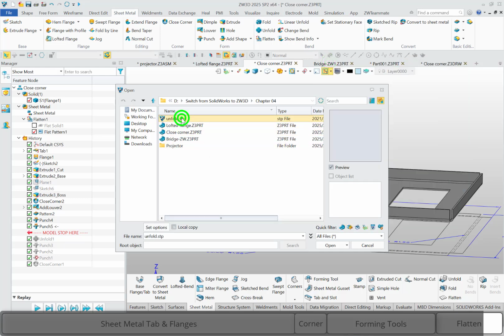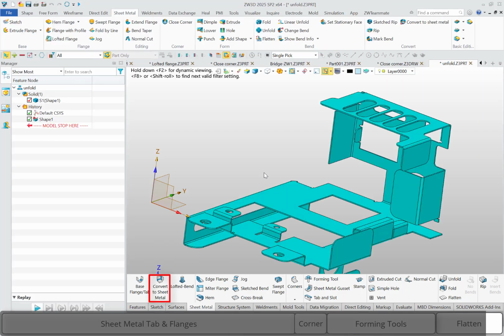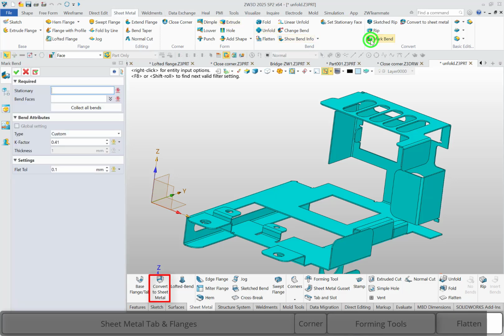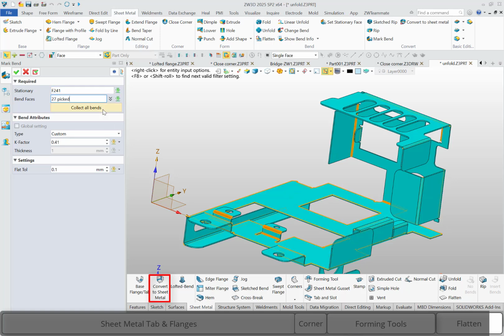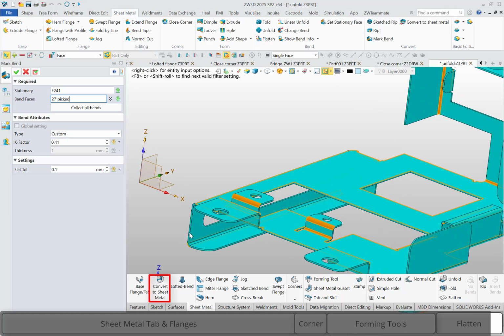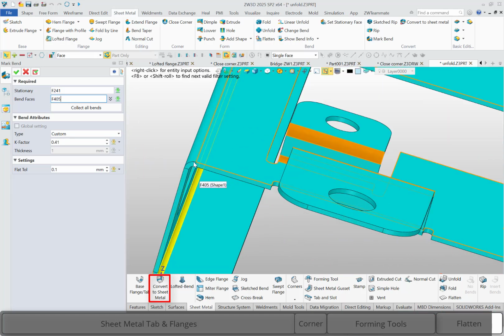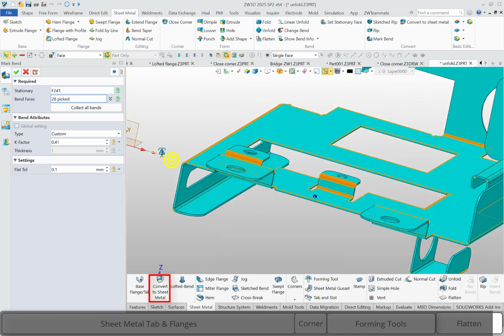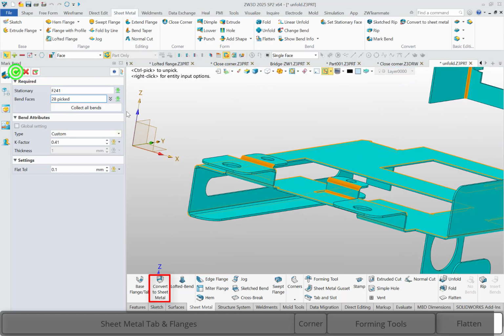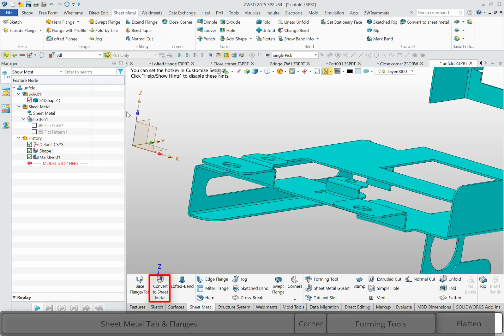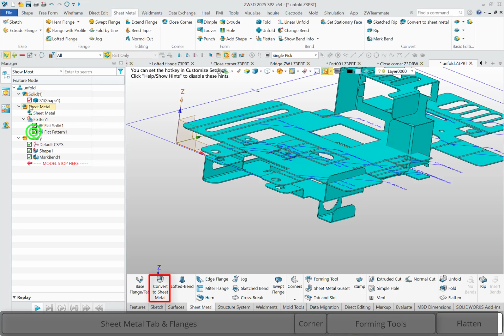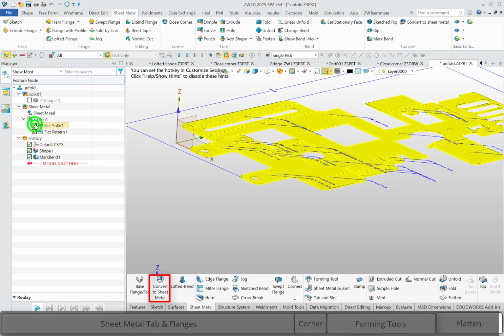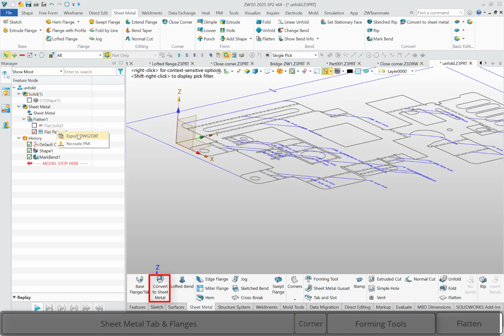After we import the sheet metal file, we can use direct edit or healing to clean up the geometry. And we use the mark bend tool to detect bends and thickness. If some bends cannot be detected, you can edit manually. Here we have one. Okay, we can apply. Now it's already a sheet metal part. And you can see the flat pattern and the flat shape will be generated automatically. Then we can export the drawing as DWG or DXF as previously done.